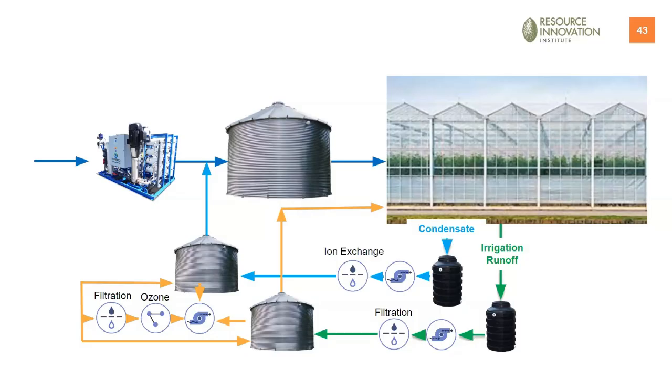And then you may want to take that condensate and run it through a small ion exchange resin bed, because condensate can often pick up heavy metals from the HVAC equipment or the building structure itself. And depending on your crop, they could build up to a level that could harm the growth of the crop. And I know in the cannabis industry, they can't have any metal ions added into the system, because that'll make their finished product non-sellable. So often there'll be ion exchange. It's pretty easy and not very expensive to add to that. And then it'll go to that clean water storage tank.